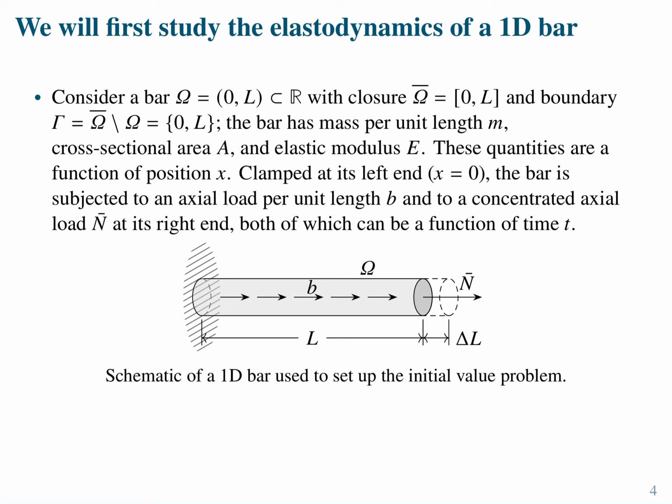I'm going to have some mass, or let's say force per unit length, that you see here with the symbol B. And I'm going to denote my bar with omega. So that is basically the domain of interest. So I say, well, consider a bar omega. It is basically a subset of the reals, so it starts from 0 and goes to L.